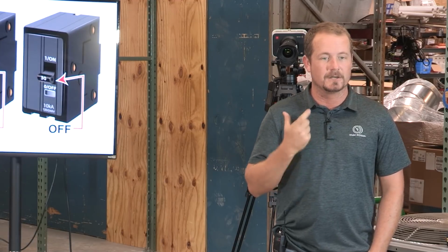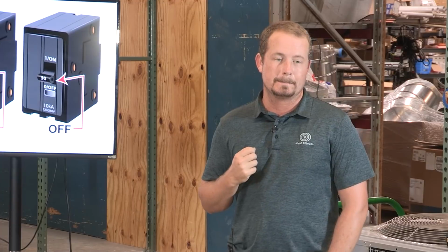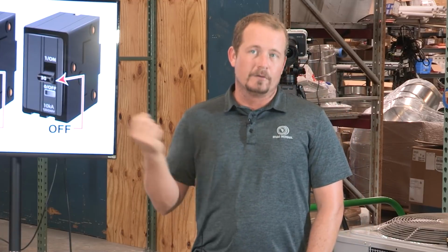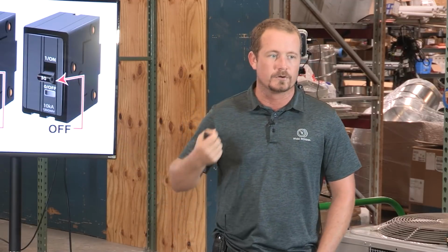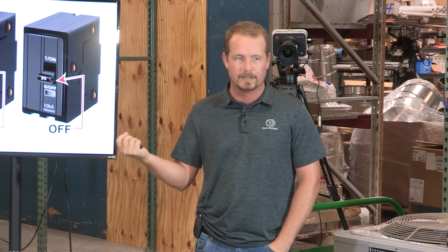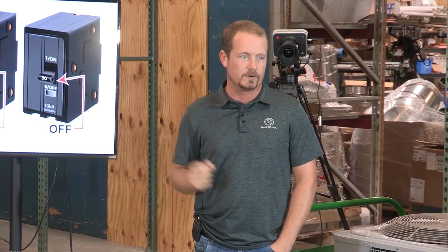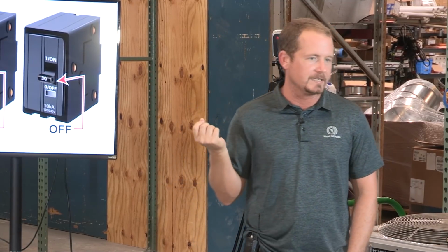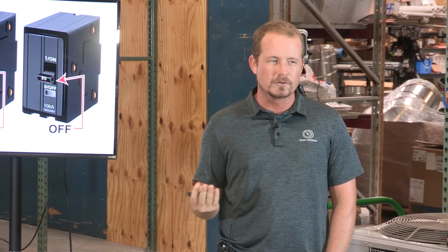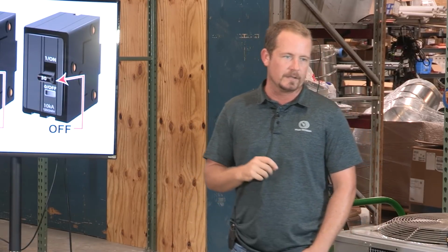What makes a circuit breaker a circuit breaker? Can you manually open the circuit? You can manually close it usually. So it opens the circuit just like a fuse or a fusible link. Fuse is just short for fusible link. It means it actually opens the circuit and then stays open. A circuit breaker generally means resettable. I don't know that that's a universal rule, but when we say it, that's what we generally mean.